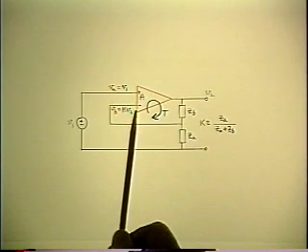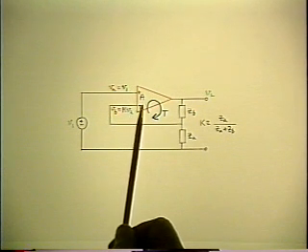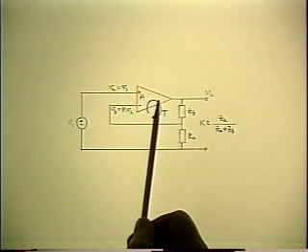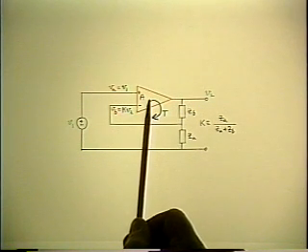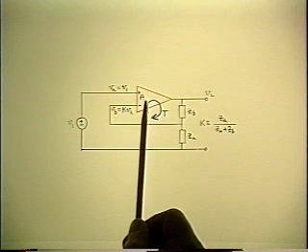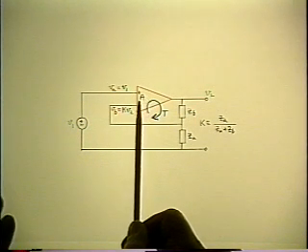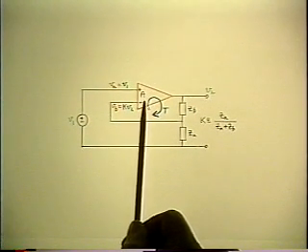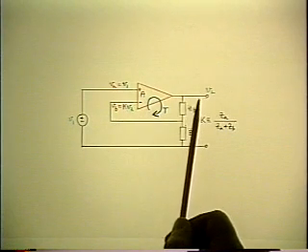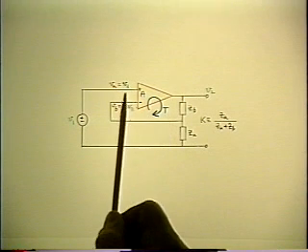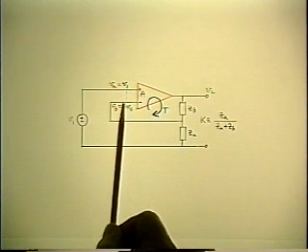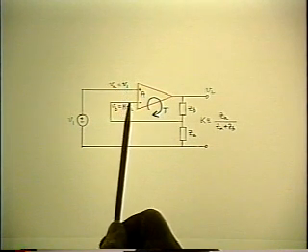Well, the usual thing that happens is you make the assumption that the A box is infinitely large gain, which is a pretty good approximation, isn't it? And the reason you do that is that whatever the output voltage is within its dynamic range, if the gain A is large enough, the error signal or the differential signal at the front end becomes vanishingly small.